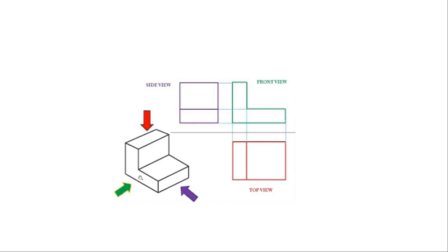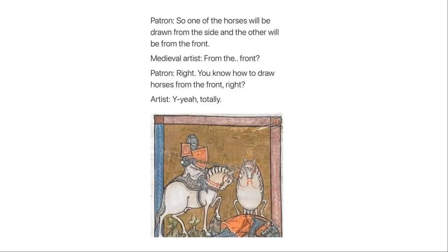We started to see this front plane, we get to see this idea of this L shape. We cannot see what's above, we only see this from the side. From the profile, we can only see this and this. That's why we see this big rectangle combined with a smaller rectangle. From the top, we only see this and this. And so again, this is what different views will allow you to create, and it allows you, when you're drawing, to eventually think in 2D but think in 3D at the same time.